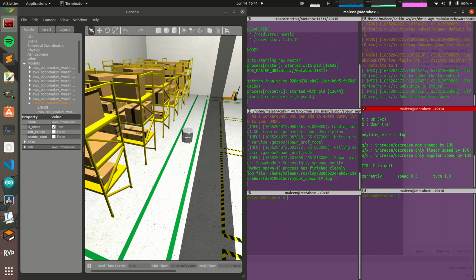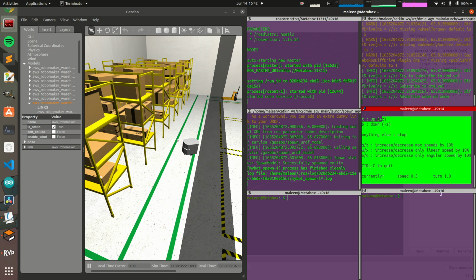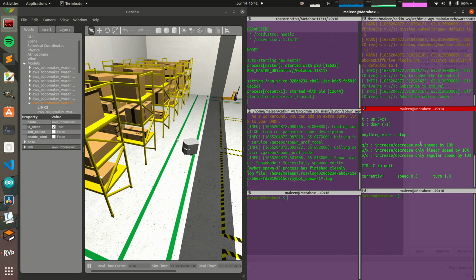So just spend some time and play around with this. See if you can control the robot and make it go wherever you want it to go. See if you can drive the robot using I, J, K, L, U, and O. Okay, so this way you can control the robot through Tele Operation. And if you press K, it will stop. Just to remind you again, make sure you click in this area for this to actually work. This has to be active.